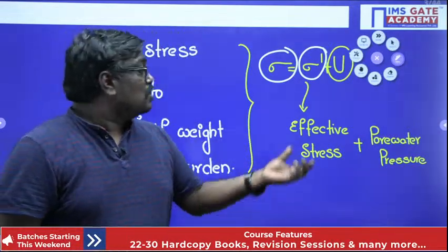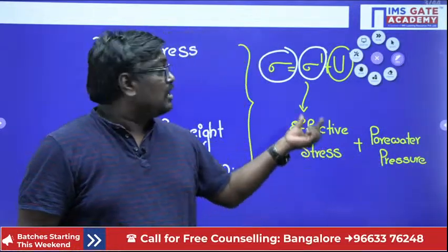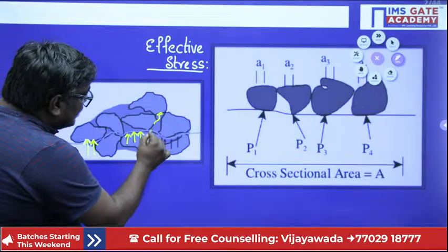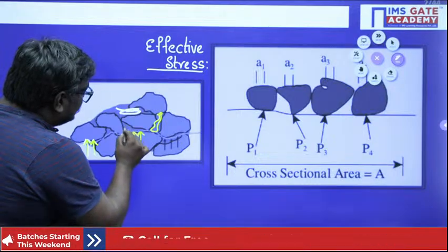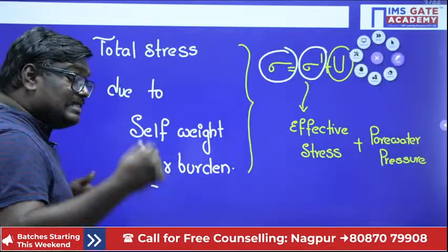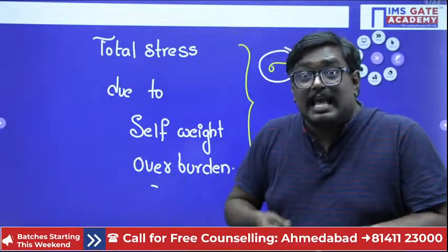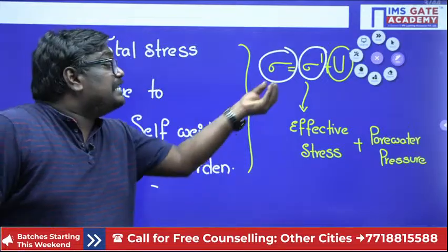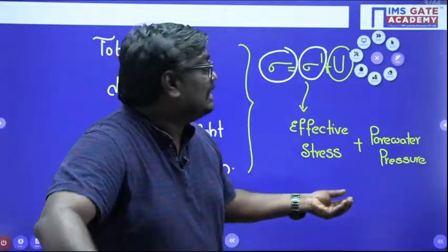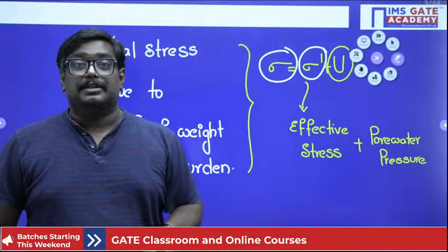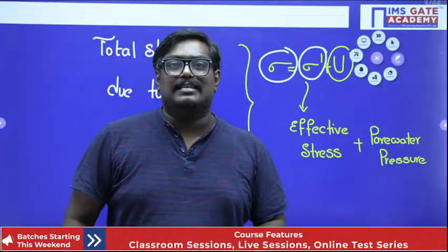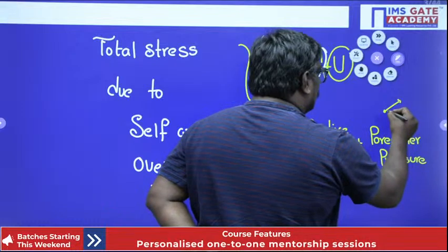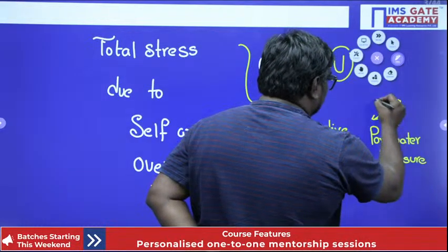So here when I talk about pore water pressure, if you see, students, in between the soil particles, there are some voids. Whatever is in these voids can be filled with air or water. If the voids are filled with water, whatever pressure is developed due to the water is nothing but the pore water pressure. And remember, my dear students, Pascal's law states this, a very important concept in earth pressure. For now, just remember this.